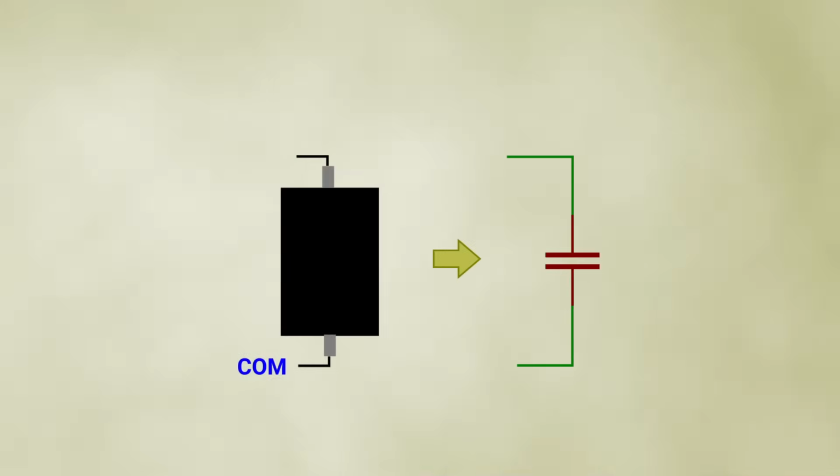Electrically, each segment behaves as a tiny capacitor. Apply an AC voltage and it turns on. No signals, it stays off. But never use a DC voltage, as it damages them over time. The AC voltage and timings are handled by the LCD driver.